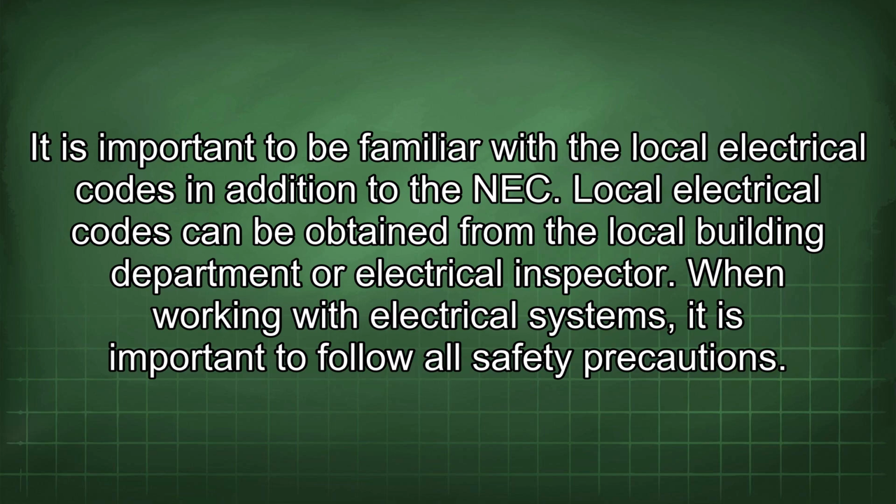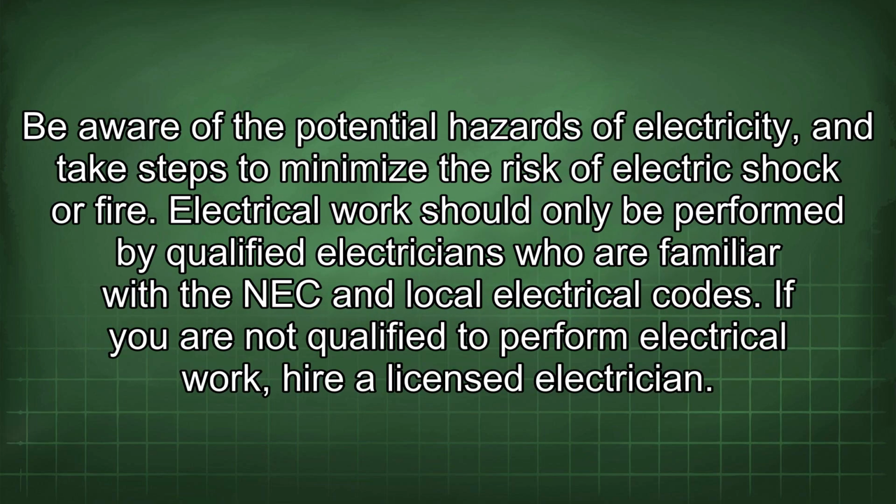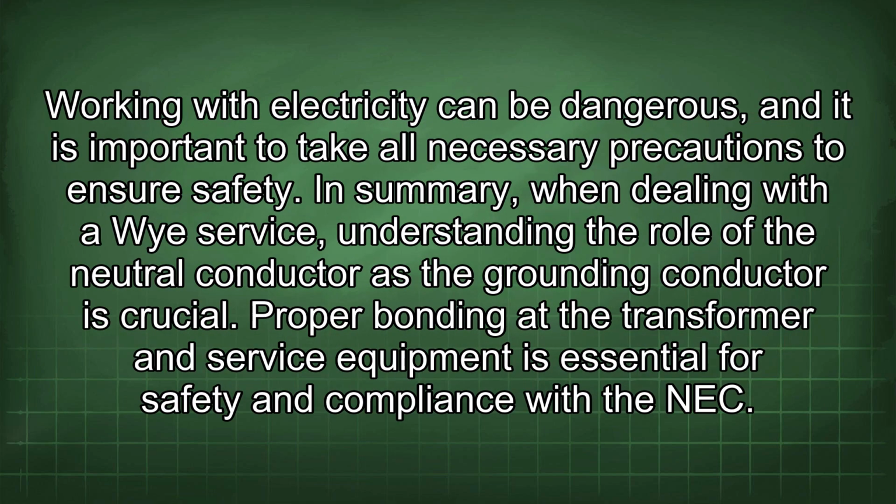When working with electrical systems, it is important to follow all safety precautions. Always de-energize circuits before working on them. Use appropriate personal protective equipment, such as gloves and safety glasses. Never work alone. Be aware of the potential hazards of electricity and take steps to minimize the risk of electric shock or fire. Electrical work should only be performed by qualified electricians who are familiar with the NEC and local electrical codes. If you are not qualified to perform electrical work, hire a licensed electrician. Working with electricity can be dangerous, and it is important to take all necessary precautions to ensure safety.